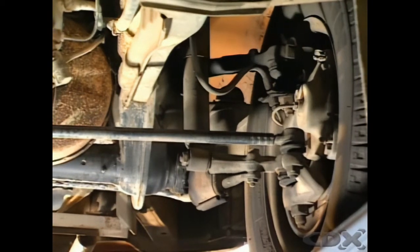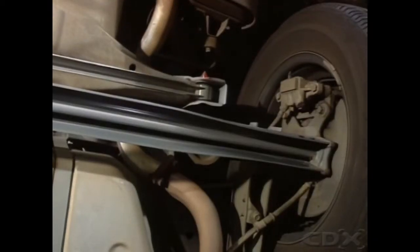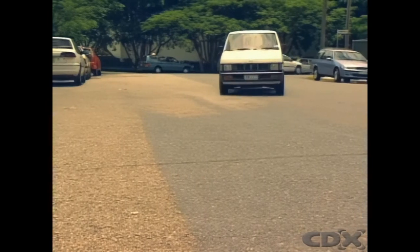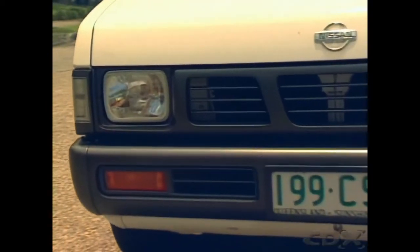Torsion bars can be used across the chassis frame on the same principle, in a trailing arm suspension, or as part of the connecting link between two axle assemblies on a semi-rigid axle beam. After a lot of use, a torsion bar can sag. On many vehicles it can be adjusted to allow for this.